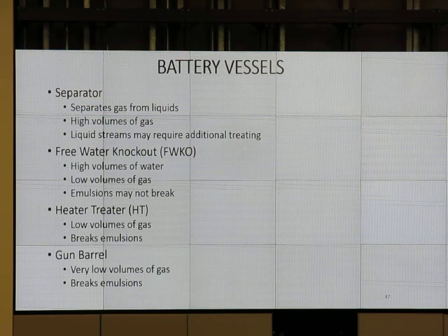So if I have a two-phase separator, I'm going to get gas, and then what am I going to get besides gas? The liquid. Oil and water. If I have just a gas well that produces some water, I'll just have water and I won't have to worry about oil. But if I got oil and water coming off that two-phase separator, I've got to do something else with that liquid stream. If I've got a three-phase separator, will the oil coming off of it be pipeline quality? Don't know. I may have to run it through something else. Will the water be clean enough to go to a disposal system? Don't know. I may have to do something else.